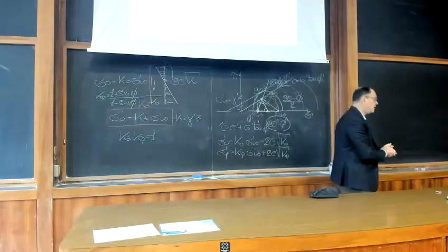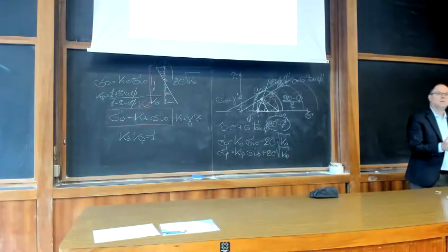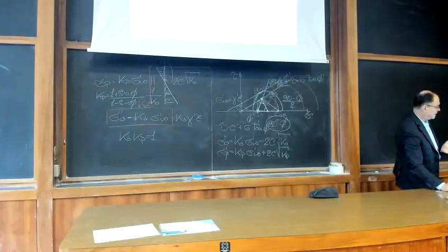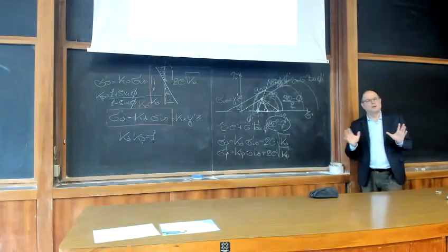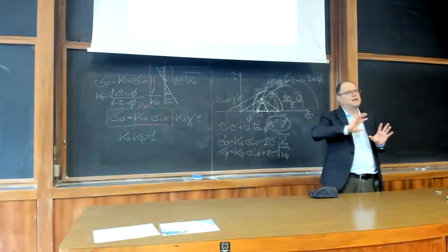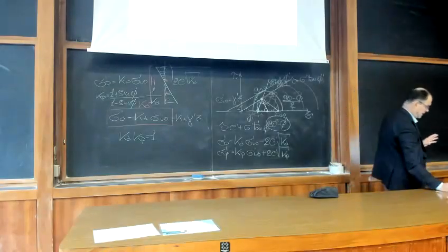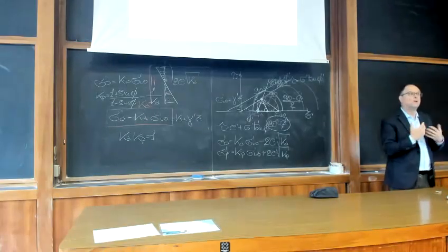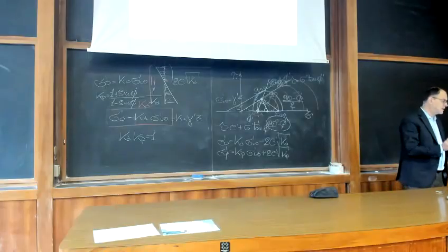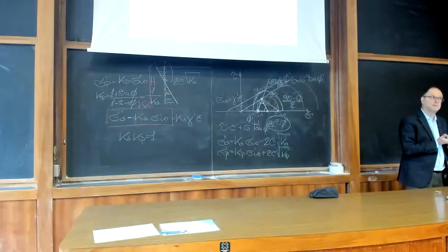But of course, a proper design of a shallow foundation must consider also the serviceability limit state. Because once we know that we will be kept far from failure, still we have to check that under the design, the exercise, the working loads, the settlement of the structure must be within tolerable limits.